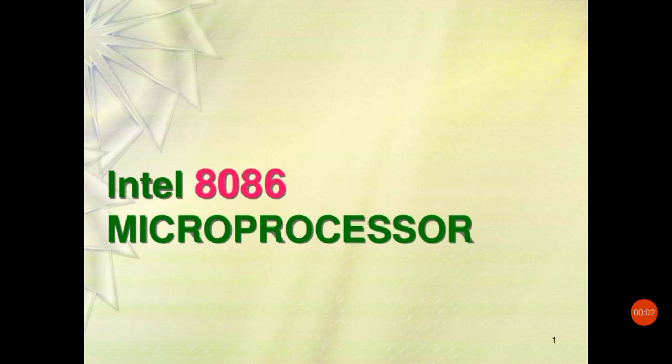Students, in today's lecture I am going to start a new topic, that is the 8086 microprocessor. In the year 1978, Intel came out with the 8086 microprocessor, which is a 16-bit microprocessor implemented in N-channel depletion load silicon gate technology, that is HMOS technology, and packaged in a 40-pin dual inline package.